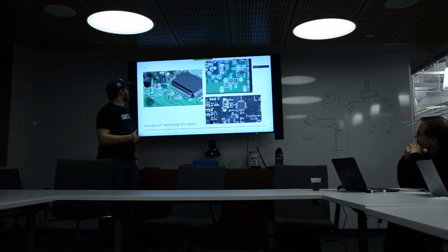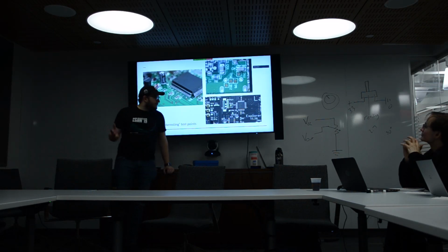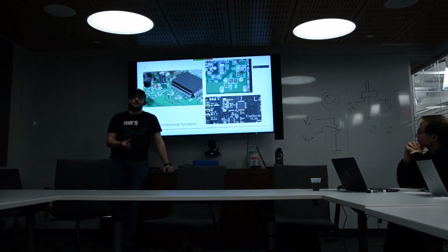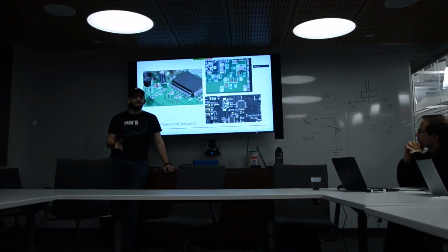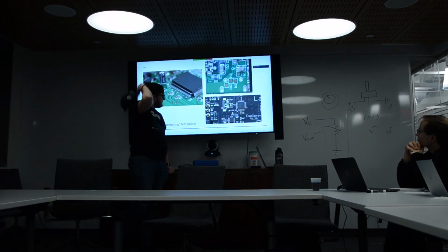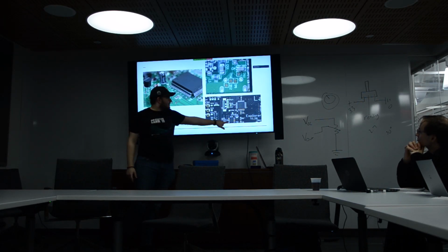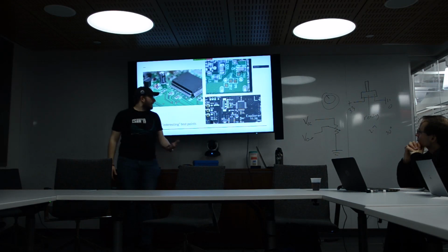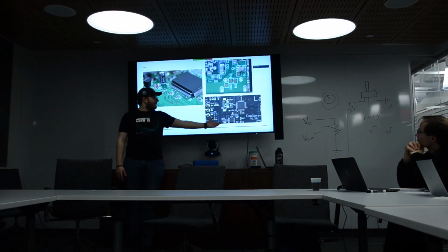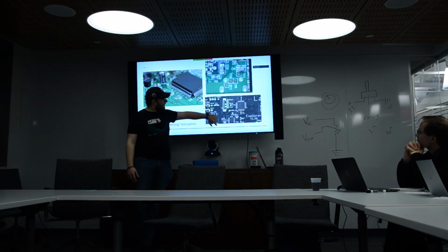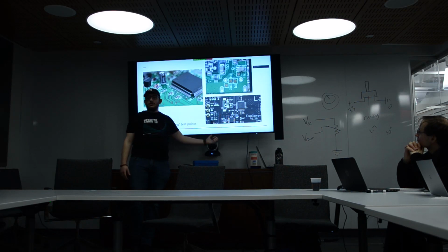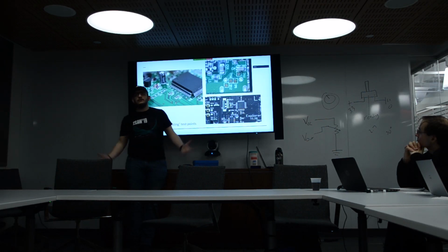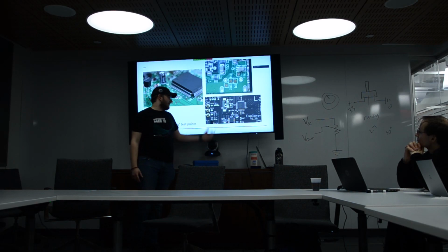I don't have it on this slide, but we talked earlier about pulling flash chips for getting firmware, right? What that means is that sometimes, so let's pretend that this chip, for example, is a flash chip. I don't know what it actually is, I haven't looked it up. But if this is a flash chip, we can easily put a chip clamp over it, and we have access to all of the lines, and now we can use a flash dumping program to just get the entire contents of that chip off, unless it's using protections, which it's not. This is, I believe, a $30 device. It's not using protections.